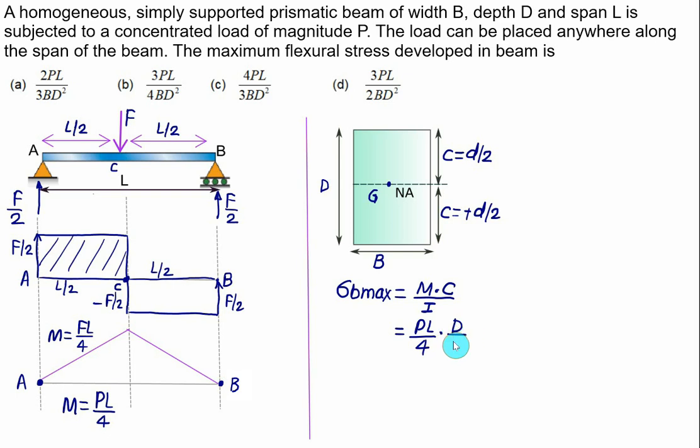So we have capital D by 2. And the moment of inertia is BD cube by 12. So we have B into D cube, and 12 will be written in the denominator. So this one is 4 and 12, so we have 3 in the numerator, and one of the D will get cancelled. That is, the square term is left.